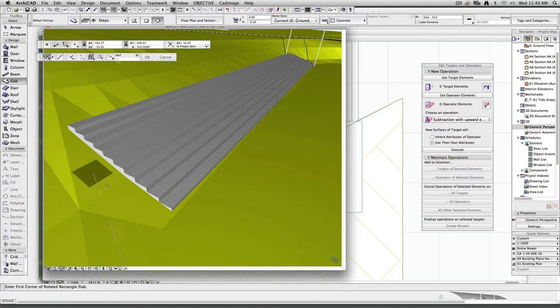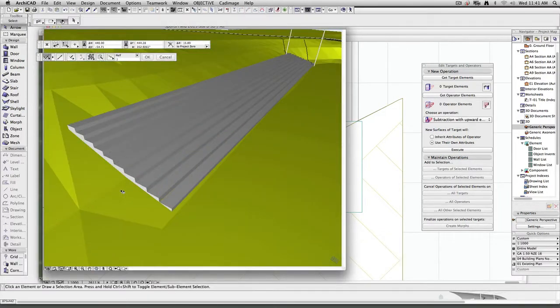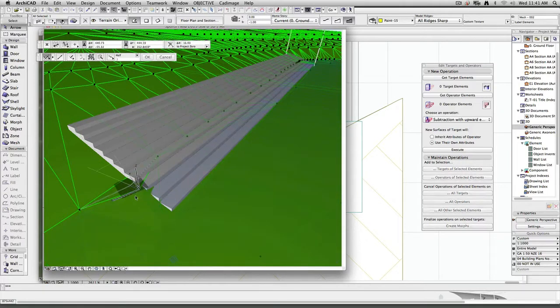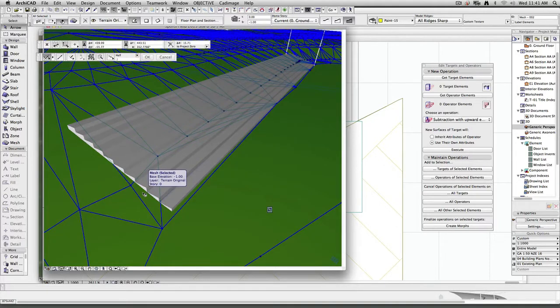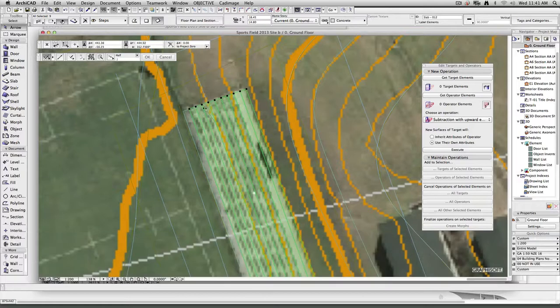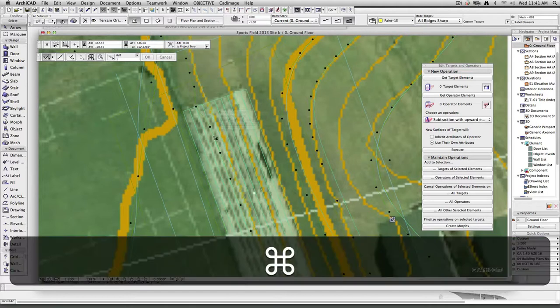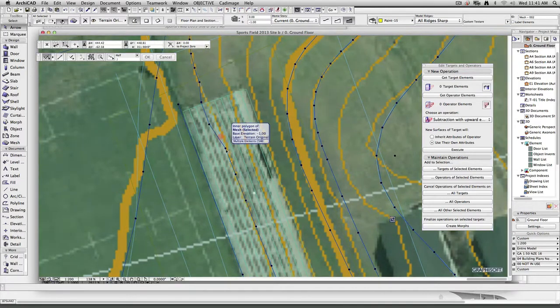Awesome. Okay, so this is very dependent on you having the slope nice and even through here. I can actually move points around, so I can see there's a ridge here. You can see that I can move this around right up to about here before it starts getting buried. So you can manipulate the contours afterwards. But then I'd have to really drop into here and make sure, see there's that contour? So I could line that contour up with that. Oopsies, make sure you only move the contour, not the entire mesh zone. So you can do it afterwards as well. You can manipulate it a little bit.